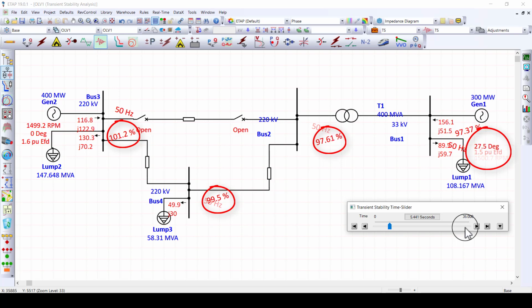Here, the power angle is increasing to avoid changing the generator speed, to maintain the frequency of the generator constant at 50 Hz, and also to maintain the synchronization of the generator. As you see, the power angle is increasing by the time, and the output electrical power is directly proportional to the power angle as we learned before, so the output electrical power of the generator is increasing as you see by the time.